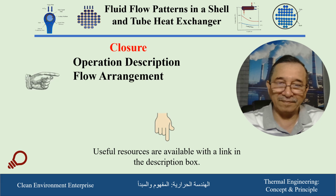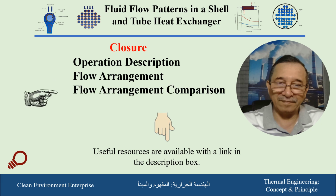And we have mentioned the counterflow and parallel flow arrangements. And finally, we compared the available flow patterns, and we have arrived at the point where we prefer the counterflow arrangement when we want to apply it for industrial application.